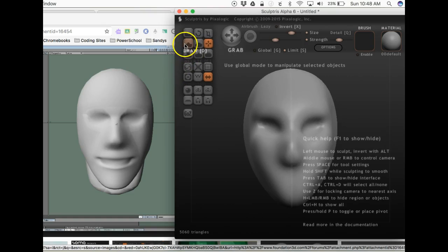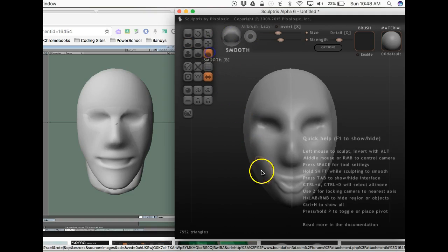Now the mouth, we have a draw tool, which works pretty nicely, and you can draw the upper lip here and the lower lip. And I know this looks kind of weird, but this is kind of the beginning. And again, you could use the smoothing tool and smooth all this out. And then to get the inside of the mouth, there's a crease tool, which is here. I just caution you that this is little dots, but once you kind of get the creases where you want, you can smooth it out after.